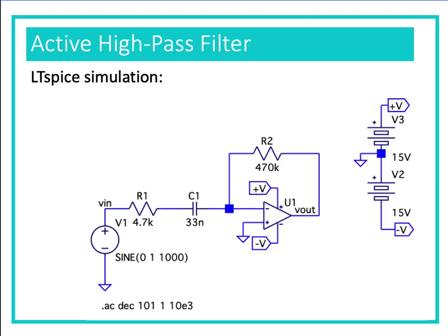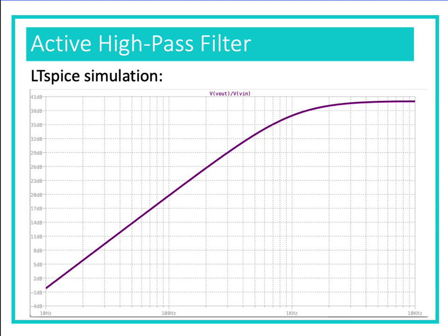We go through, and again in LTSpice, we make a circuit, and this is pretty much similar to the other one, and we run it, and we get the following response. The high frequency gain is 40 dB, which is good. And as far as finding the minus 3 dB point, we have an arrow going over to where it intersects with the trace, and then we drop down and we get a break frequency of 1 kilohertz. And that's awesome, because that's exactly what we designed it for.